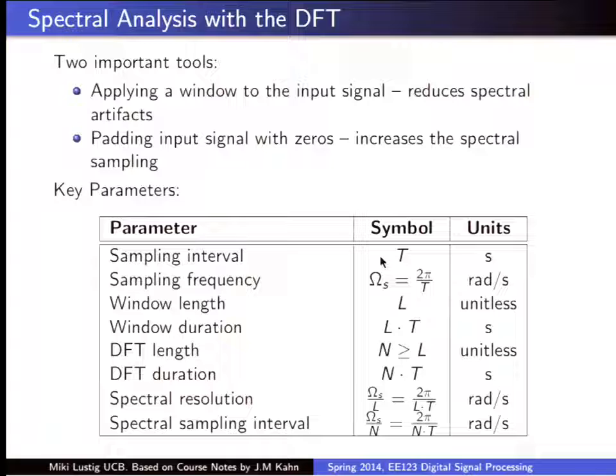We're going to pick a window length, which doesn't have units. Okay, this is going to have a certain window duration over time. The thing is, I need to remember what I did. Because when I give you samples, you just don't know what the time interval is. So you need to remember what the sampling frequency was, to correspond it to the particular time. Okay?